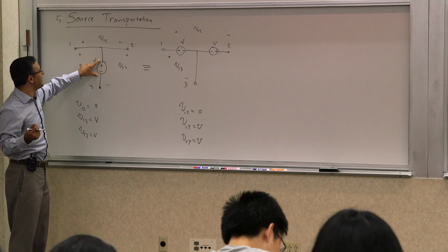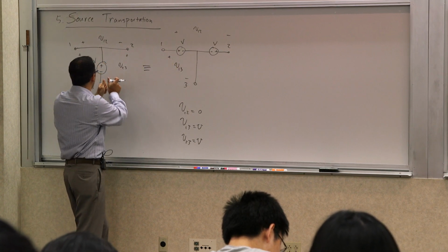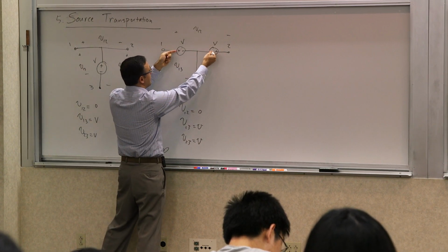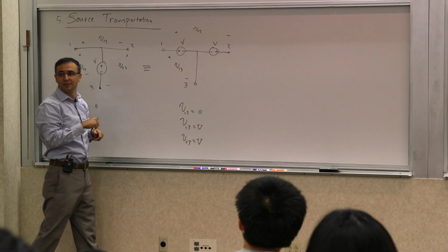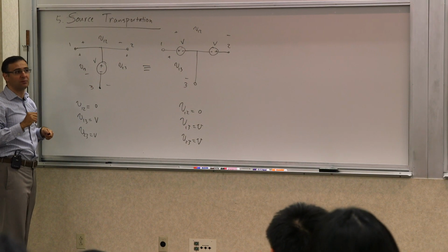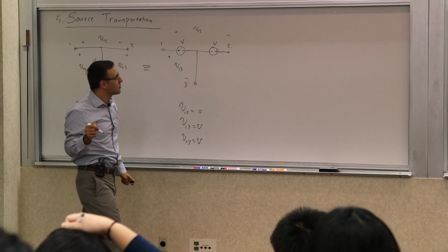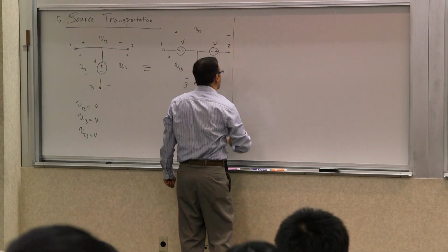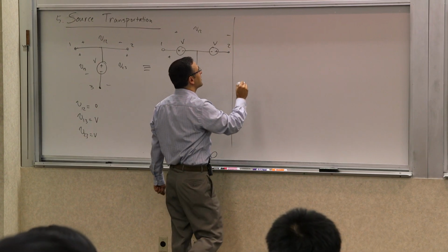So you can always replace this with that. You can actually squeeze it out, or if you have 2 that are identical, you can absorb them into one thing. So that's the one for voltages, but we know that everything has a dual. So what is the dual of that for currents? Well, the dual for currents looks like this.